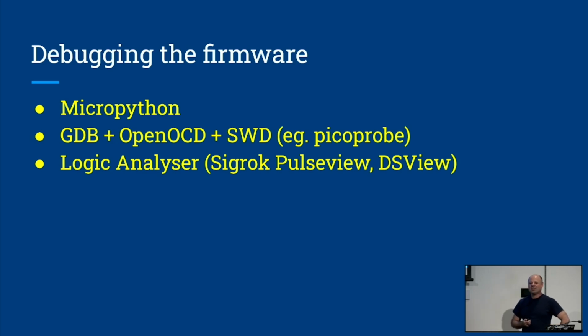Debugging firmware, wow. For a person who's done mostly mobile development for the better part of 10 or 15 years, this was a revelation. For those of you developers in the room, keep your hand up if you use a debugger of some sort. Excellent. Have you ever thought about only having a maximum of 4 simultaneous breakpoints? Oh yes. Perhaps it's worse on other microcontrollers, I don't know, but that's the maximum number of hardware breakpoints that you can have when you're debugging on the RP2040.